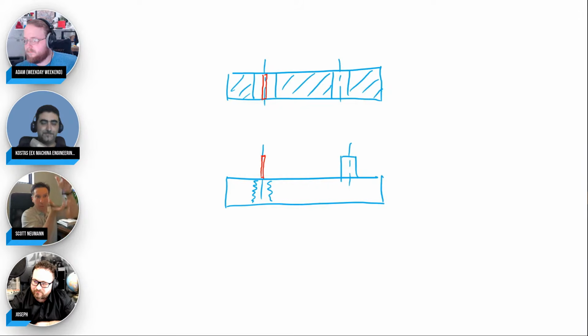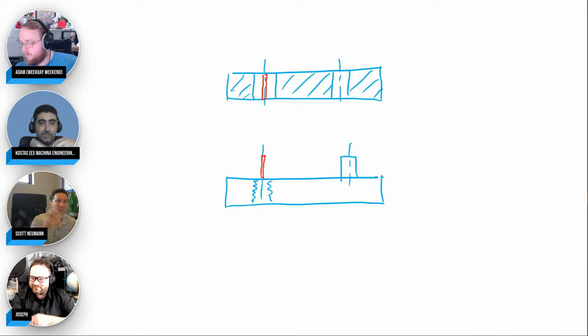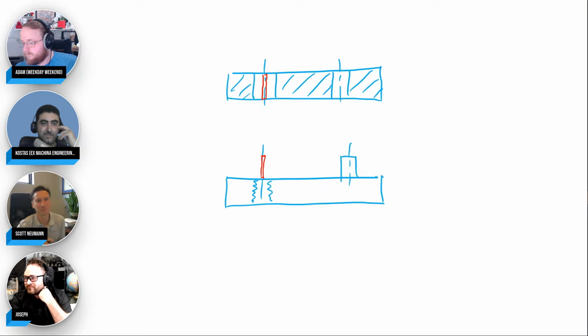And that way, when I put these two parts together in the CAD, then the tolerance zone will overlap with the tolerance zone, and you're back to a really easy smallest hole, biggest pin calculation. So it's like you're ghosting in a part that's not there and then tolerancing it, because that's what matters. It's the part that's going to do the work.